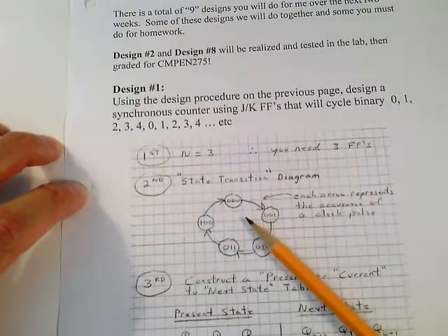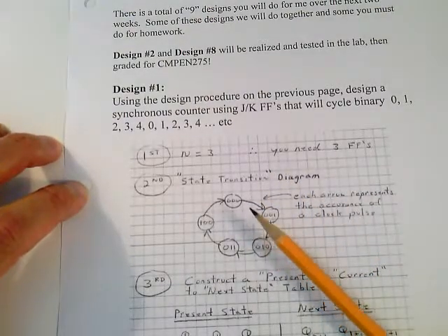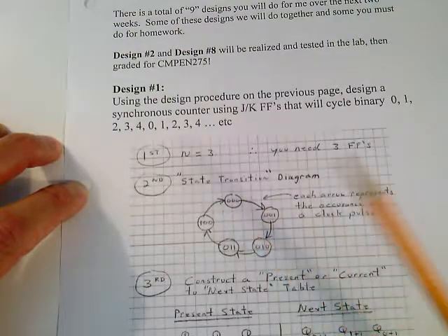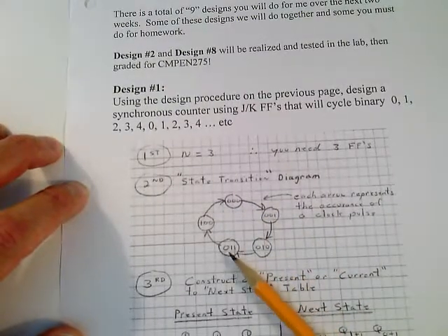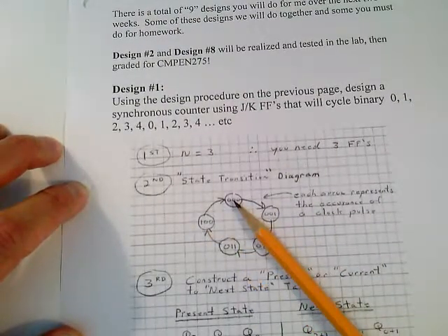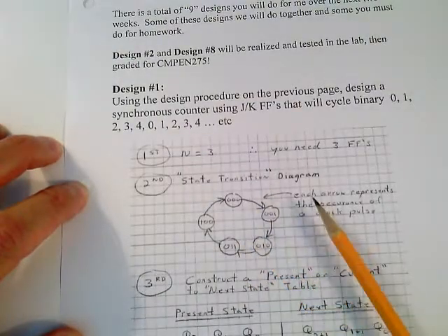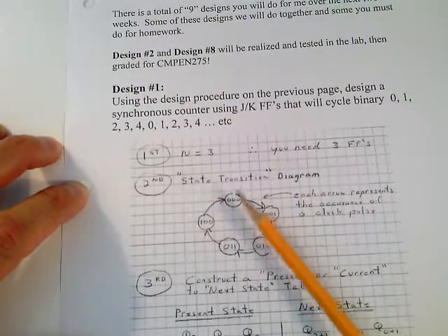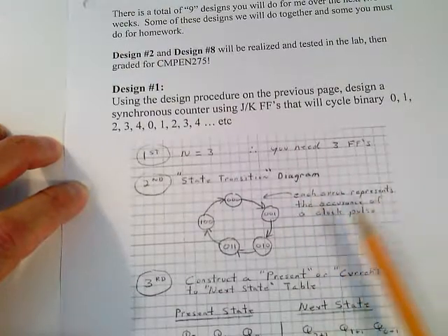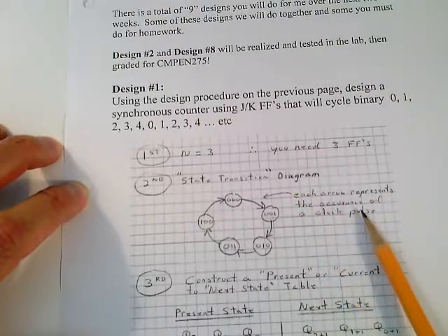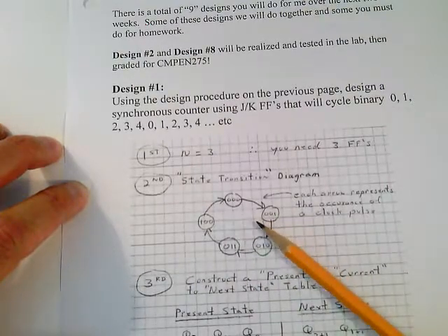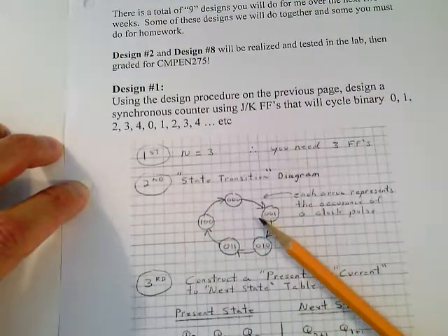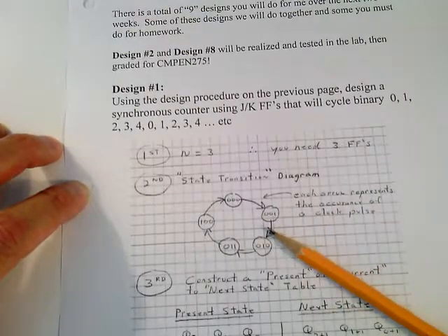So we're taking a look here, and at this point there's no input conditions we have to deal with. We basically have our states, and our states are 0, 1, 2, 3, 4, and it goes back to 0 again. That's the procedure. Remember I told you on these state transition diagrams, each arrow represents an occurrence of a clock pulse, and each circle is a state. Very simple to go to these state transition diagrams. Well, they start out pretty easy, but it's not a difficult process.